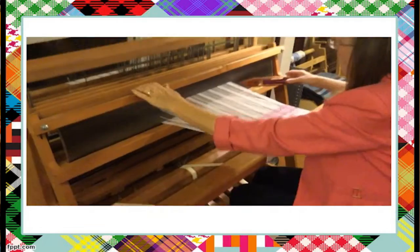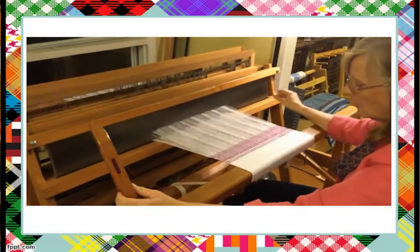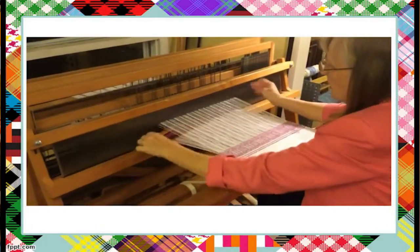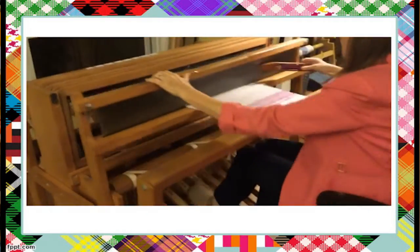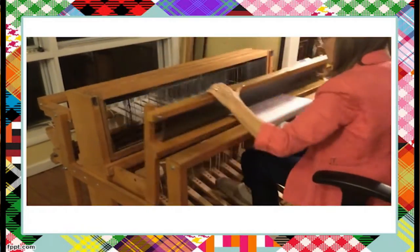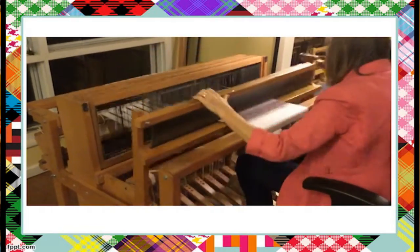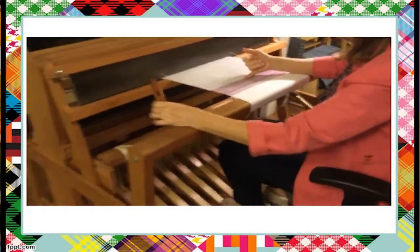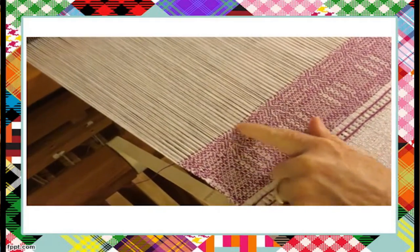Next, this video is an example of how to use a hand loom machine. In the video, we can see that the person using it controls the up and down of the harness to separate the layers. Then, using a shuttle to carry the thread across the loom. And last, she uses the reed to push the new loops against the old loops. Then, keep repeating this step. After a few times, we can see the pattern come out.